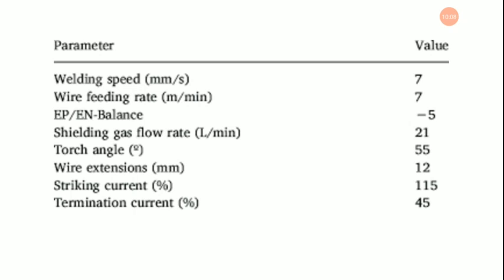As the base current increases up to 98 ampere, the penetration value goes on increasing, and after 98 ampere, with further increase in IB value, there is a decrease in penetration value. As the base current increases, the value of penetration is higher. This is because IB is mainly helpful in maintaining continuous arc during welding, so it melts more base metal and filler material in narrow direction, so penetration increases.